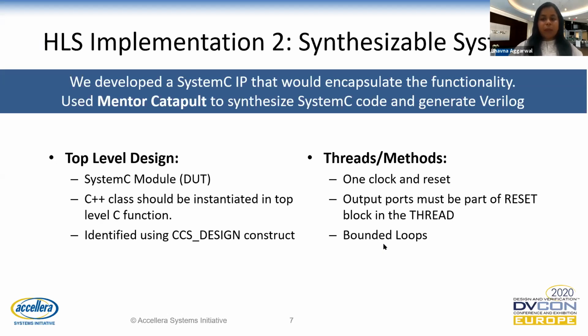The SystemC module encapsulating SOBEL functionality consists of multiple threads and methods. Each thread or method of the SystemC IP would synthesize to an RTL module. As per the SystemC synthesizable subset, we followed a few of the guidelines to create this synthesizable IP.